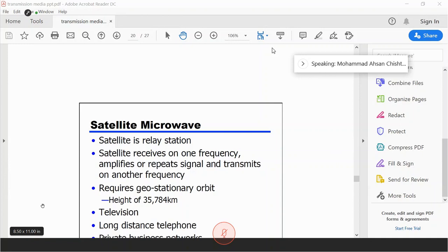Or you have to have higher towers so that you can be away from each other. So we have here a satellite in which microwaves do not pass through the buildings well. That's why, for example, another parabolic antenna is DTH, direct to home. You use Tata Sky and other dish antennas to get direct to home video transmissions. Now you put them on the walls outside, on the buildings or on the rooftops. Why? Because microwaves do not pass through the buildings well.